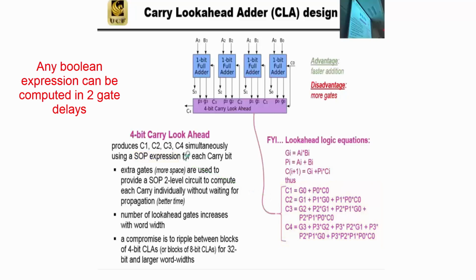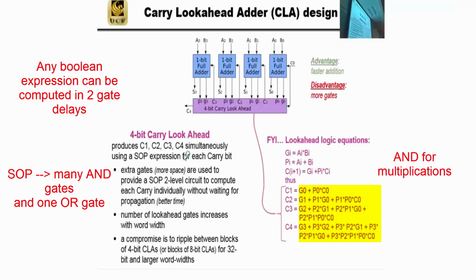What does that mean? It's a bunch of AND gates in an order. Exactly. So we can take any Boolean expression and eventually get down to a sum of products, right? I put AND gates here at this first level, and I have all the inputs here, and maybe I need wider ones, but then I OR them together and I get Z. And I can do this in 2 levels.